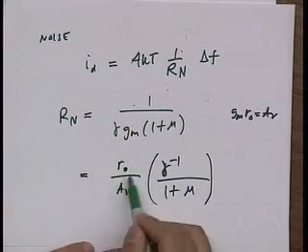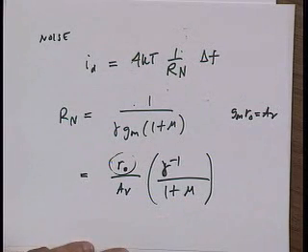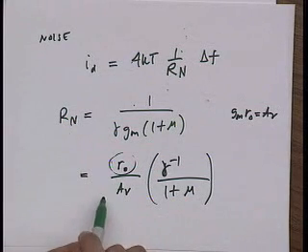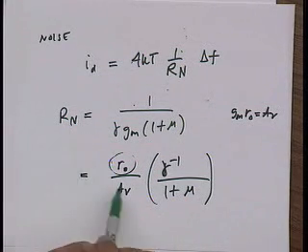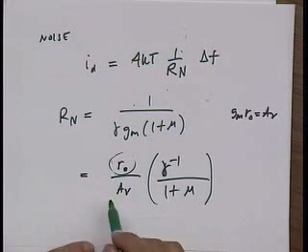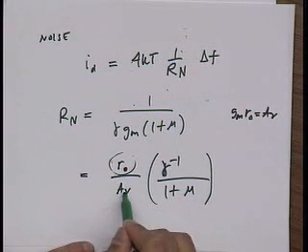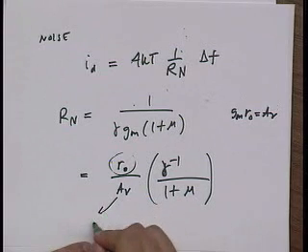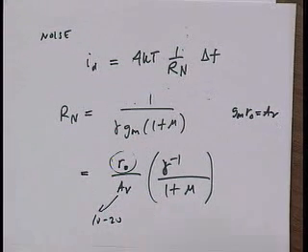And because RO is the actual resistance of the device, the noise resistance of the current mirror is actually a voltage gain times smaller, right? And this might be 10 or 20 or whatever, or 100 for a long channel device. Is that good or is that bad? Any comments?